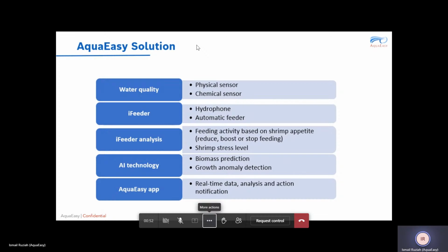And as we go into installation, some simple things. Because all these details you can actually find in the detailed deployment documents that just now Lucia showed. So I'll just go through the simple ones. So the most important thing is actually your panel position. Ideally we want to put it in the center of 4 ponds, like this layout for an example. But you have to take care of the cable limit of this 50 meters. You must make sure where you want to put your hydrophone, your sensor is within 50 meters.